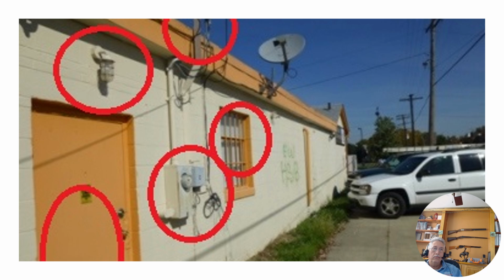So this is the other end of that same side of the building. Like I said, SWEP, surface and structure, we're looking for cracks and peeling paint. H, there's no HVAC on this side. E is electric, so we got electric light, we got a meter, and we got a masthead. W is windows, doors, and vents, so we got windows and doors on this side. So we check all those items.